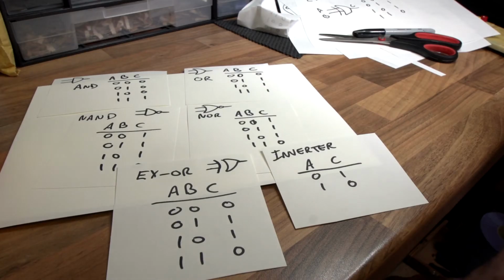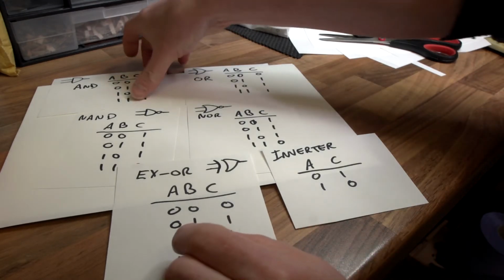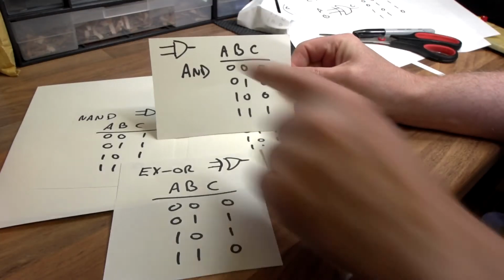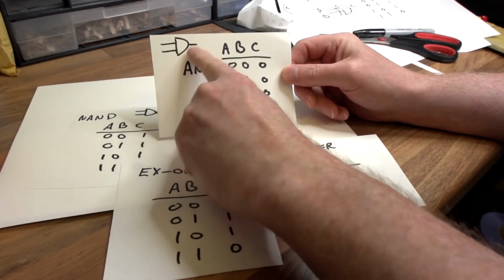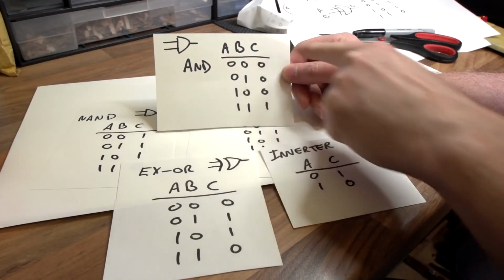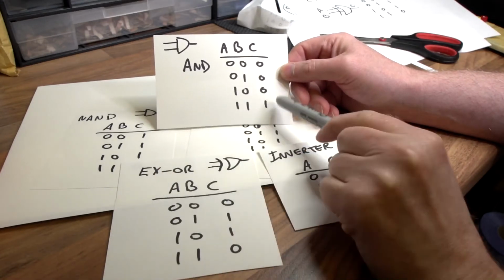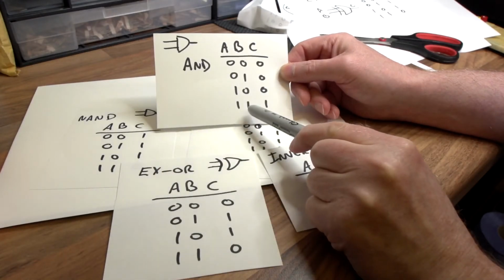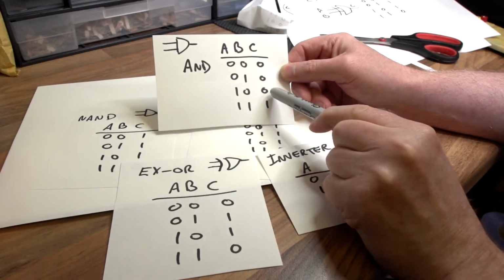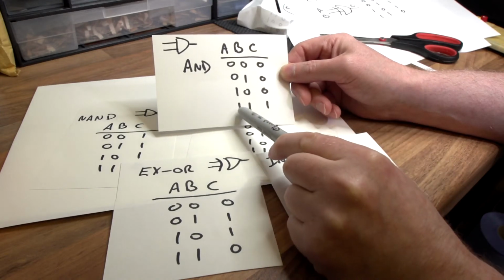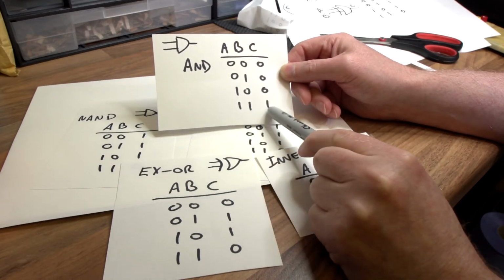Okay, so just to recap with the gates that we've spoken about so far. We're looking at 6 major building blocks really, which is the basis for nearly all logic circuits. Let's just recap. So we have the AND gate, where that's the symbol there with a straight front and a curved back. A and B, the inputs, C is the output. So you only get an output when both inputs are high or true or on. Everything else is 0. So it has to be A and B before output goes on.